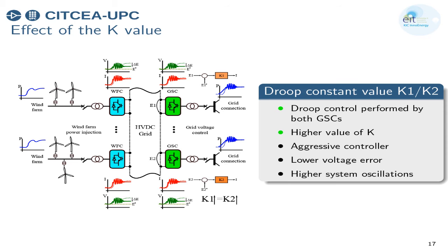When we started simulating these things, our question was: how can we design this case? Because we want power sharing, we didn't want to exceed the voltage of the grid, because we want to maintain the grid voltage between 1 per unit and 1.05 per unit, let's say.